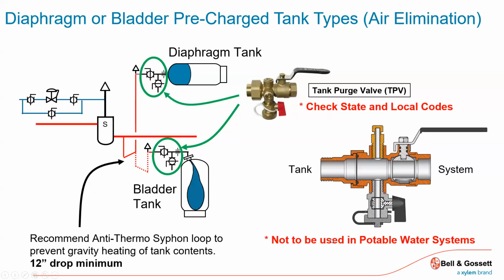And then these are just little valve connections. But the convenience of it is, if I have a way of connecting a tank, I have a way of isolating the tank from the system, and I have a drain. After it's out in the field and there's some issues going on and someone says, hey, we're going to troubleshoot it, what's the pre-charge of that tank?